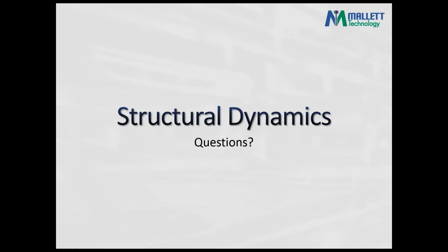Yeah, I would go ahead and add that the modes and the mode shapes, the frequencies and the shapes, you can think of them more as a property of the system rather than the actual stress or strain that it feels. Right. So once we know the excitation, then we know what multiplying factor to apply to each mode. If the excitation is right on a mode frequency, that mode's going to light up and you're going to see big stress. But you need both. I don't know if that helps. And static alone, as Steve said, has a big downfall: it doesn't capture the amplification, the true dynamic nature of the system, as Dan said, may be lost if you opt for static only.